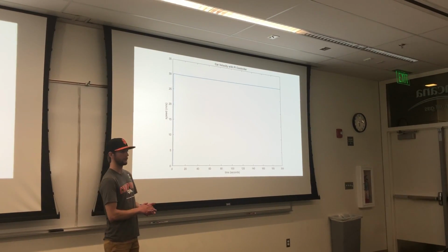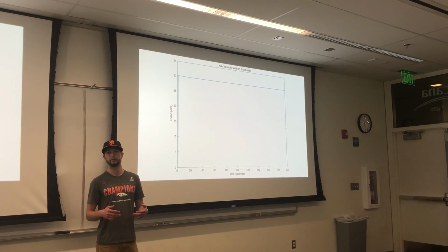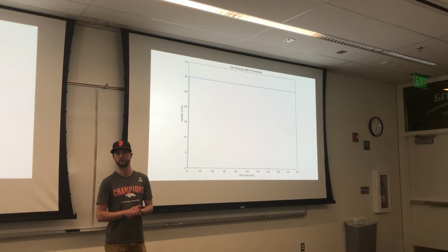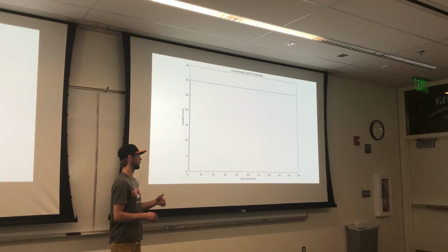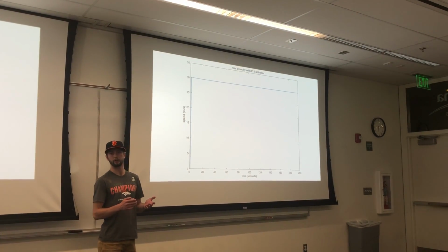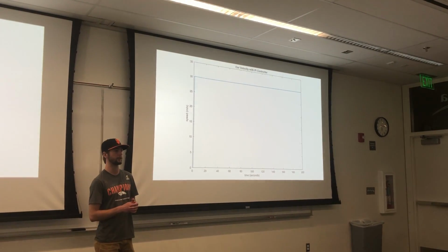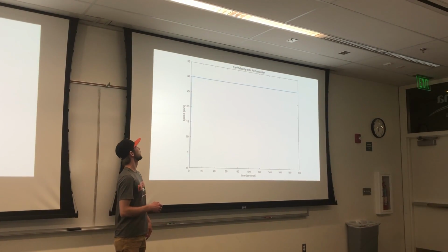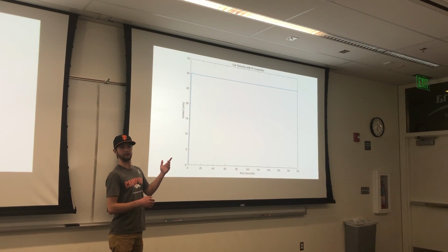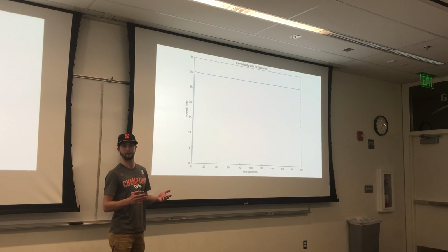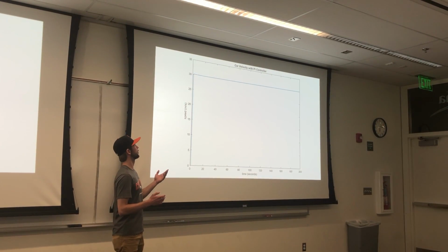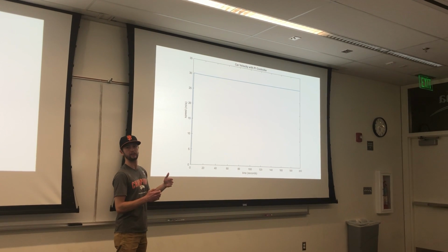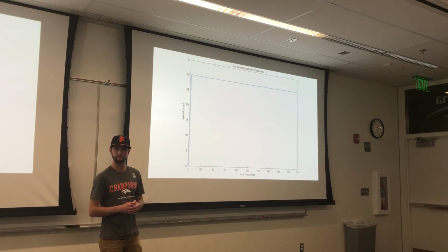All right, we also made sure our calculations were correct and verified it in a more realistic simulation in Simulink, where we put an input of 100 as a gain in our Simulink setup. As you can see, your rise time is 0, which is a little unrealistic for our situation, but this proves it has 0 steady state error and our system is still stable.